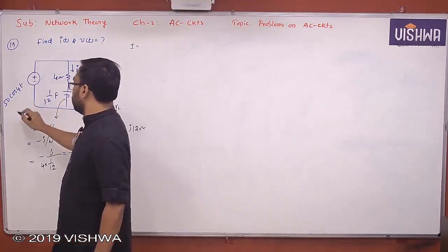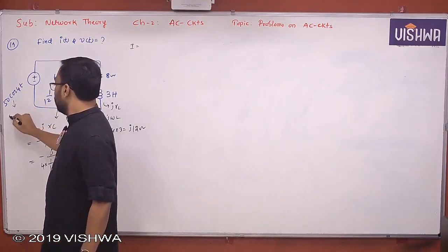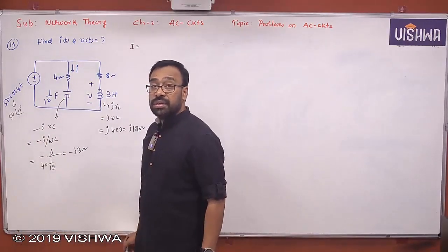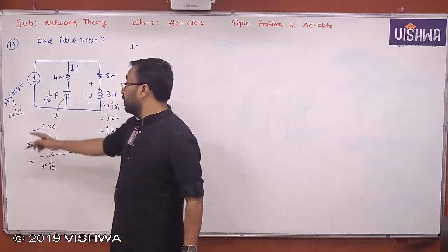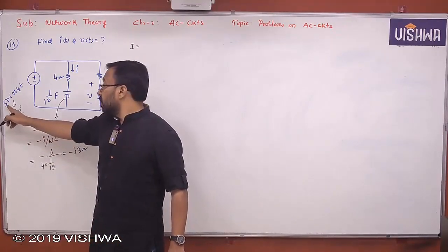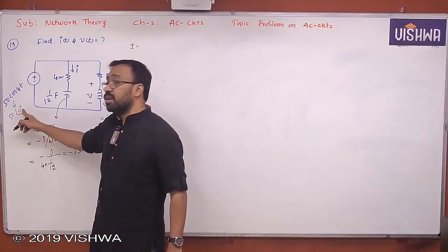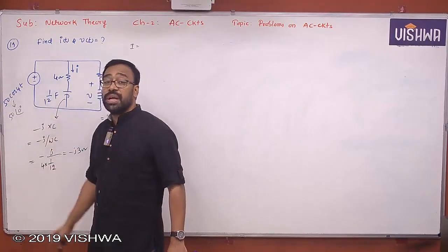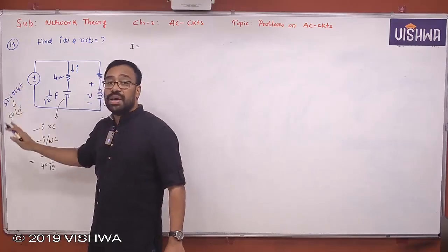Now it's very clear that I can get I is equal to, this is I, right? This is the total voltage. And what about the complex form of this? 50 at an angle of 0. Some textbooks take 50 by root 2, and some textbooks follow only 50. But remember, when you take 50, that means you are not dividing it by root 2. This is the maximum value. So maximum to maximum phasor you are taking. Then phasor to sinusoid also, when you take, you must be taking the maximum value as it is.